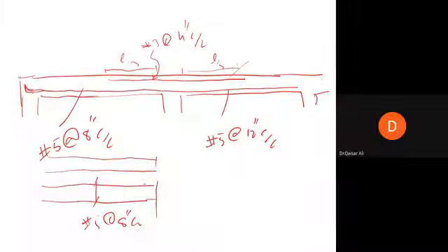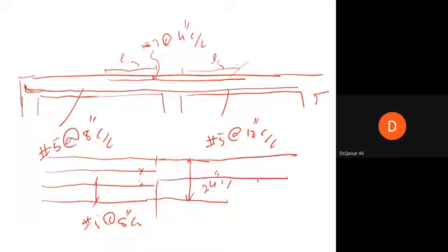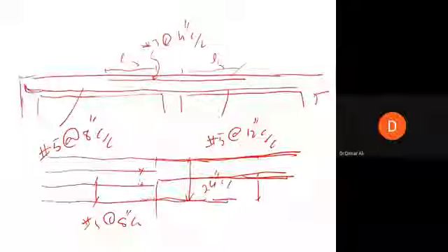This spacing is 8 inch. If we cut these two bars, this 8 and 8, and we extend this, so this spacing is now 24 inch. We'll place another bar like this here to make this 12 inch. So the spacing is now 12 inch. So we'll continue these two bars, we'll cut these two bars, so that the desired spacing is achieved. So this kind of adjustment must be kept in mind when the final decision on the spacing is made for the preparation of drawings and onward use at the site.